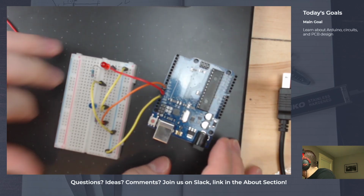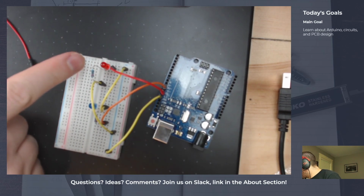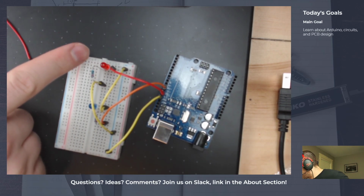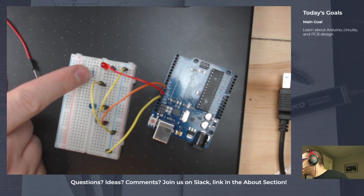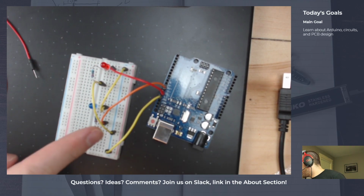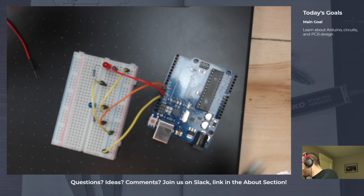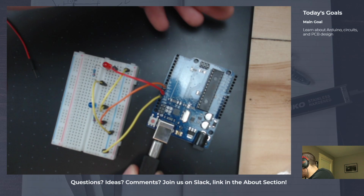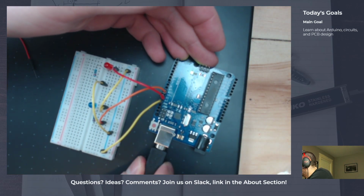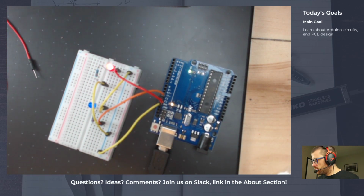Cool. So red wire coming over the LED to one side of the LED, the other side of the LED is going to a different row. That's connected to a resistor in the same row. That goes up and over to the yellow wire, and the yellow wire goes to ground, and we already connected ground to the Arduino, so we don't need to do anything else. So now we should be able to turn this on, and we'll watch the alternating colors of the two. So red and then blue, and red and blue. And now we've just moved our circuit over from Tinkercad onto the breadboard.